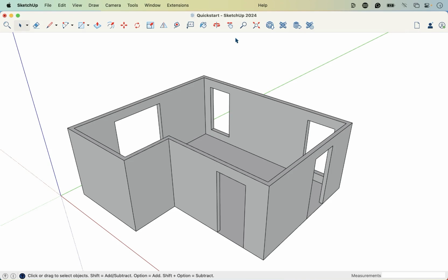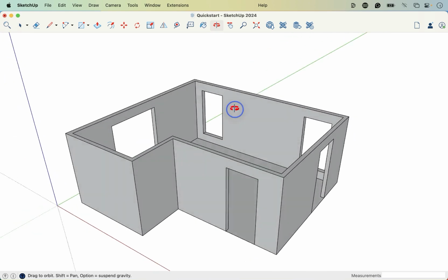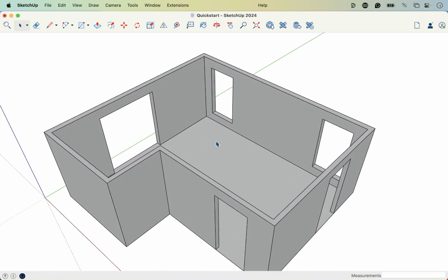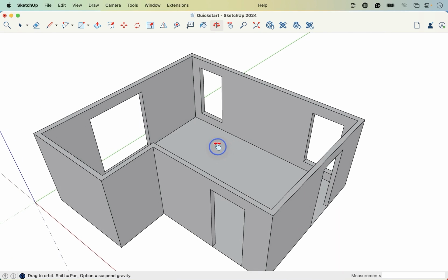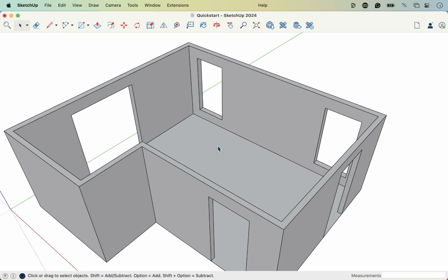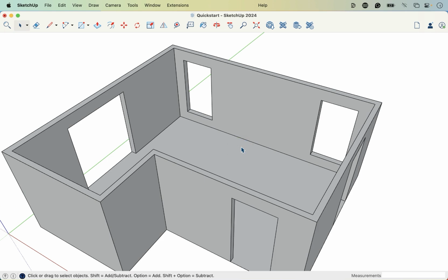In this lesson, we're going to add a ceiling, group it together, and then introduce the concept of tags. So first, let's draw the boundary of the ceiling. We're just going to do a flat one for this space. It's kind of the easiest one for an intro course to accomplish. So let's grab our line tool, L for line, and then we're going to reference the outer corners.